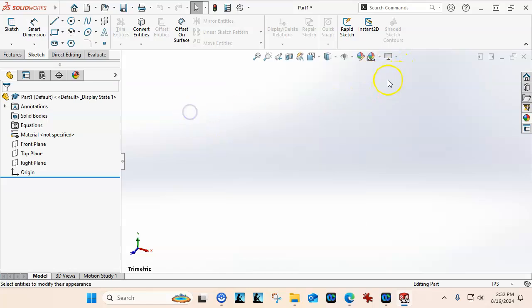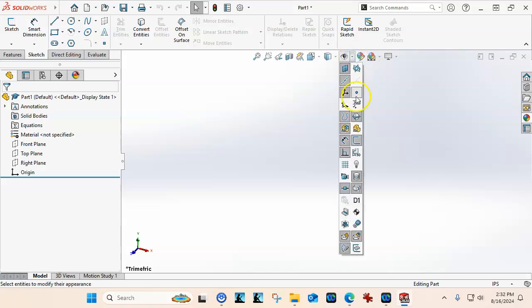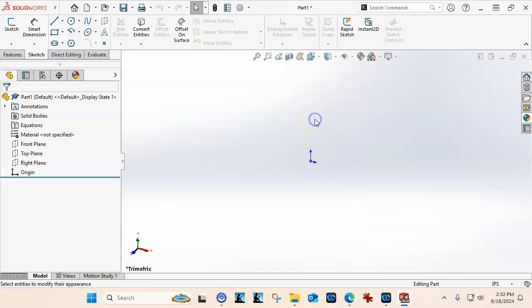plain white. Oh, and I forgot to turn the origin back on now that I mentioned that. So there is the view origin. I do like to have that little blue dot in the parts, not so much in the assembly, which we'll talk about why later. If your computer is capable of RealView, you can have all of the shiny shadows, ambient, and a lot of times those aren't very good for my videos.